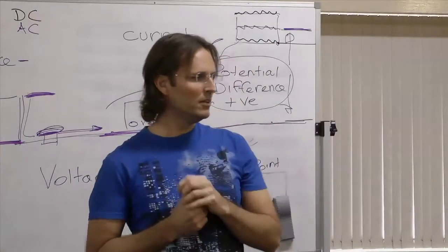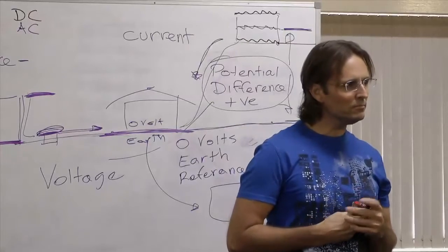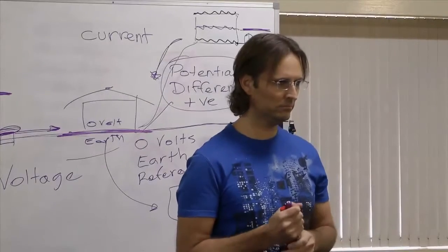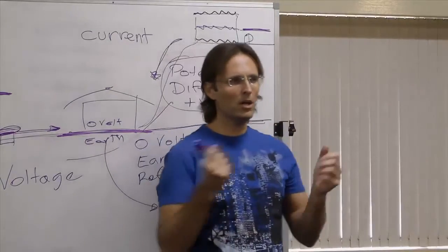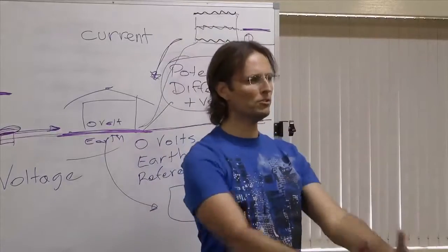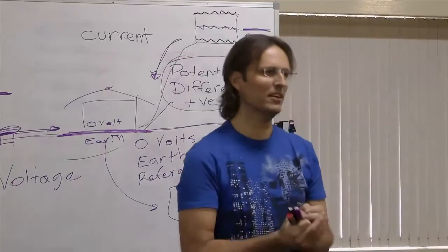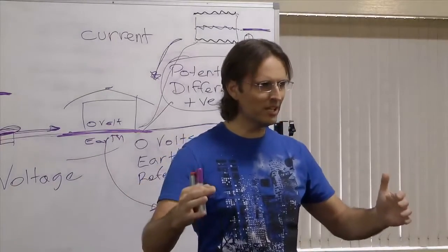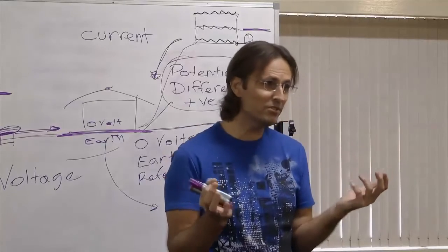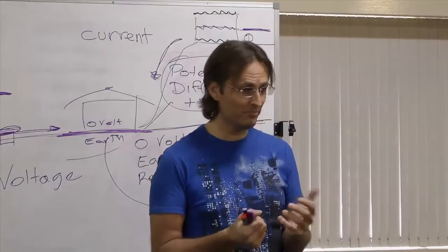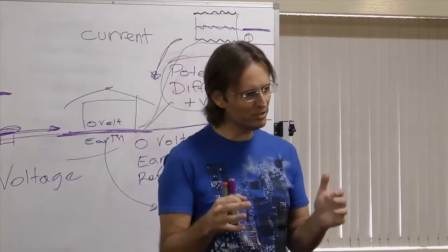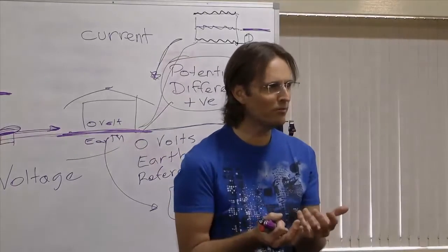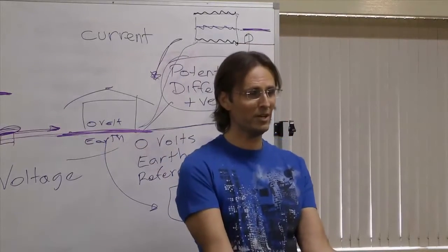Is there a potential, if a lot of energy is concentrated at one point that goes into the Earth, for it to come out anywhere else besides staying in the Earth? If the entry point to the Earth is well earthed, then there is no danger really of it going anywhere else. But you must understand that very, very high voltages, such as a lightning strike, have the potential, within a certain range from that area, to actually cause a flow of current and therefore a potential difference across that range.